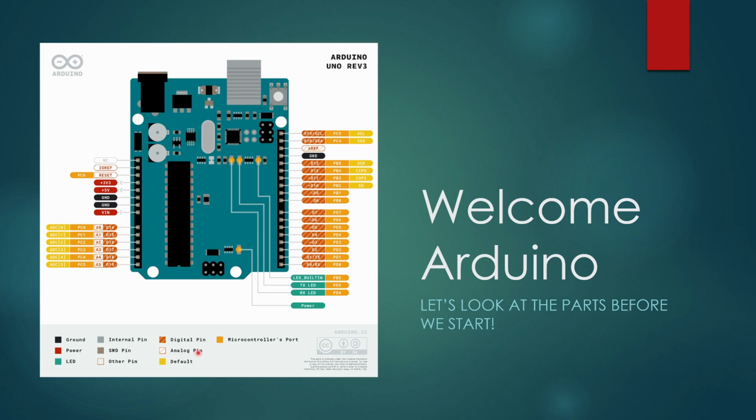We can select the digital or analog pin. So if I want to use that one in an analog way in the Arduino software, I use analog functions, and I reference it with the pin name A0. The same goes for digital, right? If I want to use this as a digital function, then internally in the Arduino software I use the digital function calls, and the reference is then the pin D14. Depending on how I interface with the Arduino software, I can use these numbers, give the Arduino software the number, and use it to control the output. And this is basically how it works.